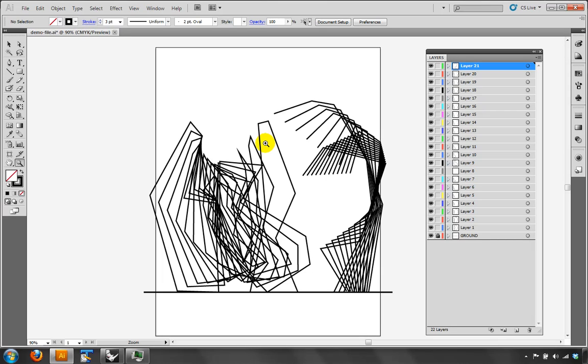We're saving it as an AutoCAD file because we want to preserve the layers. If we just import the Illustrator file, the layers actually don't come into Rhino, and of course that's a problem. We want to keep things organized.